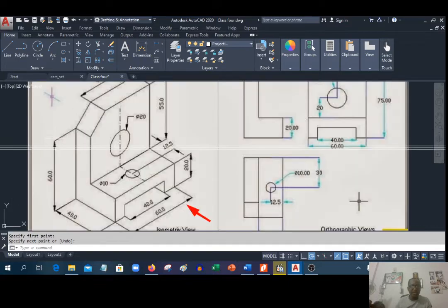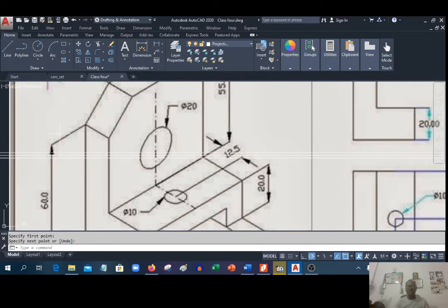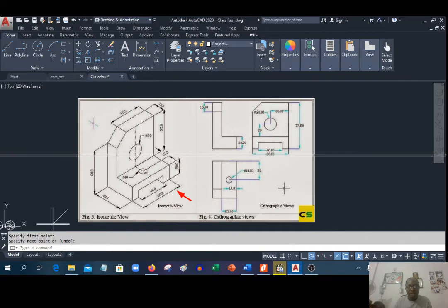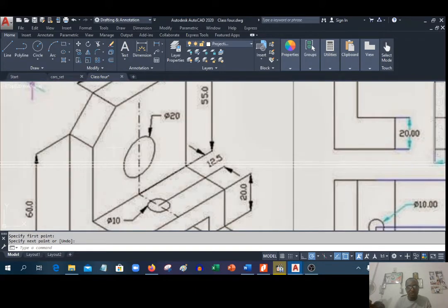Let's come back here and see this properly now. That means this drawing was not completely defined in dimension in this isometric drawing, right? The values for the location of this center hole were not completely given. What was missing was the height from this.